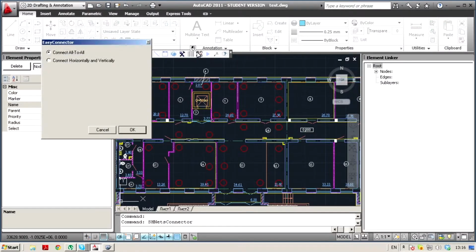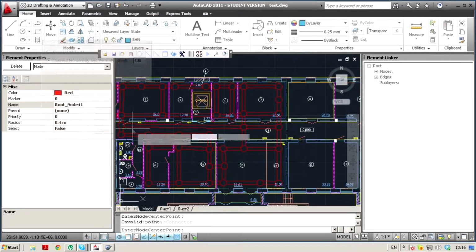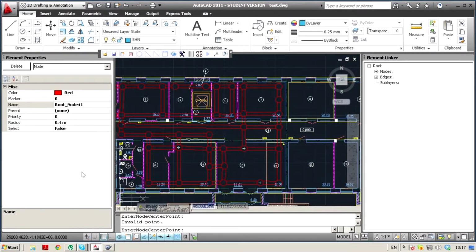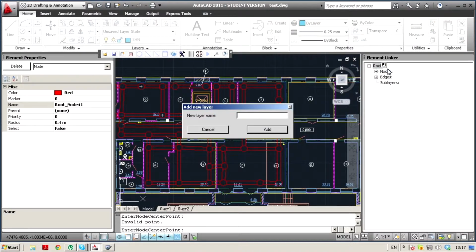You run the tool and select the item that allows one to connect all network nodes in the horizontal and vertical. Then you set the accuracy with which the line may deviate from the horizontal or vertical direction. Next, you need to define the outlet locations. This is accomplished in a new layer for outlets and cables.